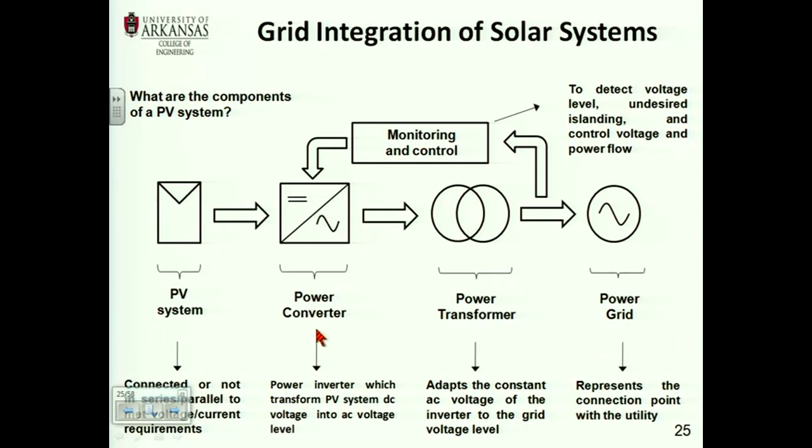But basically you need to have some power electronics every time that you go from DC to AC or AC to DC. But also you have to have some boosting action. Right, you have to boost the voltage from 25 volts to, if you are injecting into 120 volts RMS here, you need to have probably a DC bus of 200 volts, at least, right?